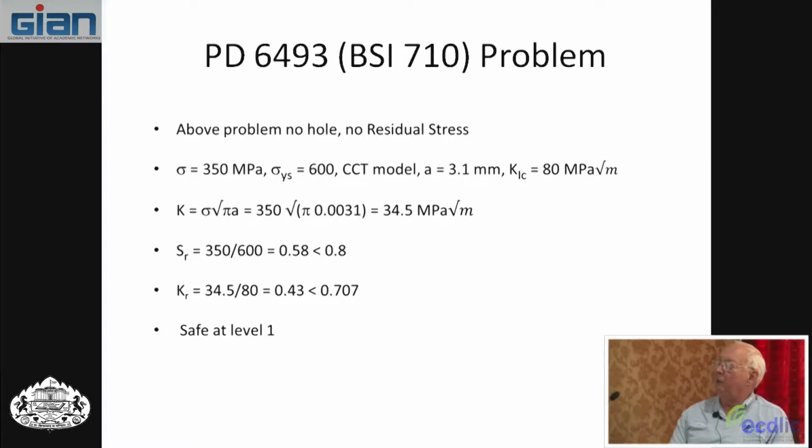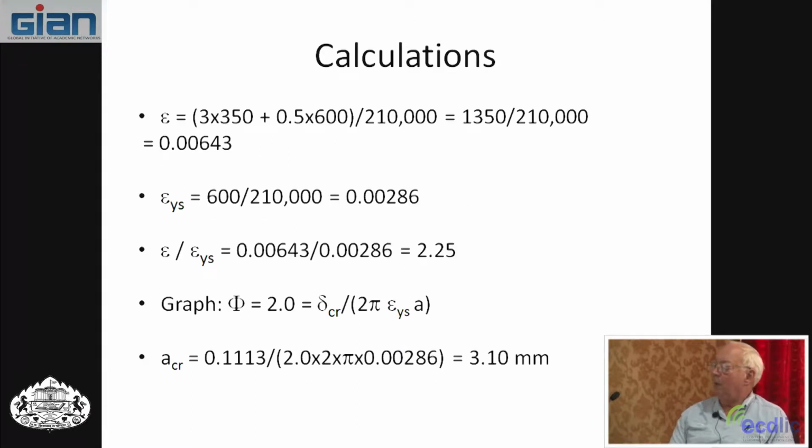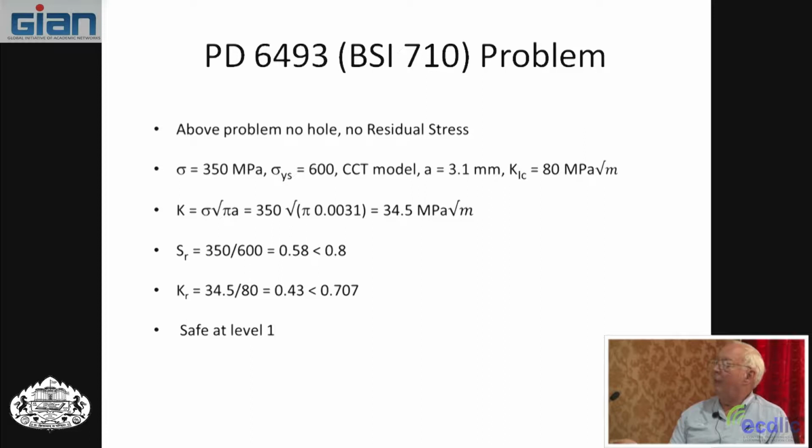I'm going to use a center crack model with A of 3.1. So I took it from here, 3.1, and K1C, which we didn't have on the previous problem, is 80. For the center crack model, I'm going to use the infinite plate model, which then has capital F of 1.